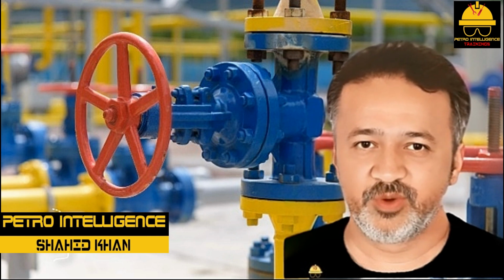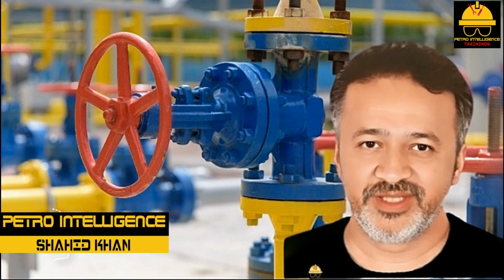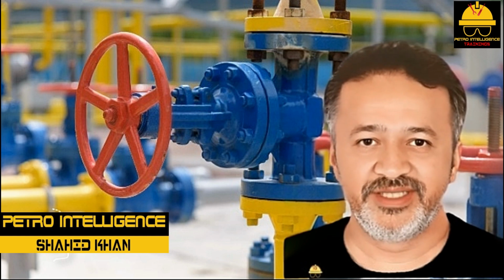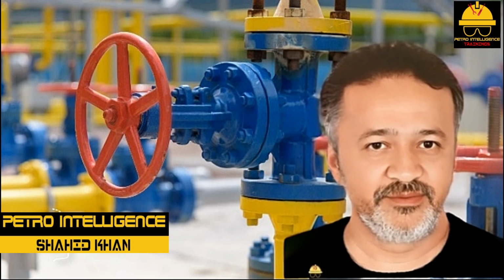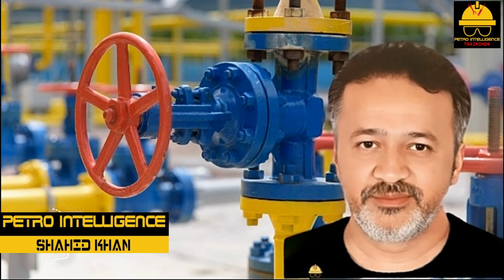The diaphragm conforms to the setting on the handwheel. Diaphragm valves typically are used in low-pressure applications. The diaphragm valve seats are made of chemical-resistant plastic, rubber, or neoprene. This type of valve does not use packing. Diaphragm valves come in two designs, weir and non-weir.